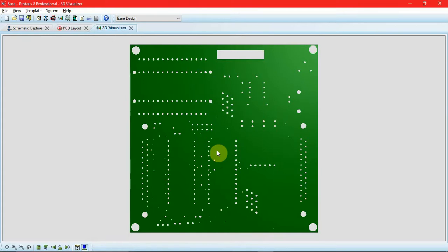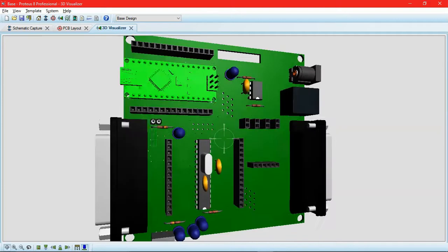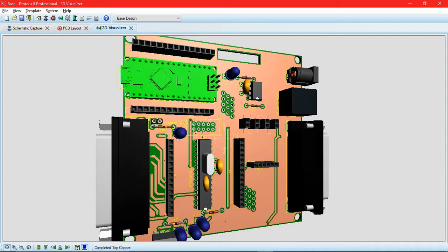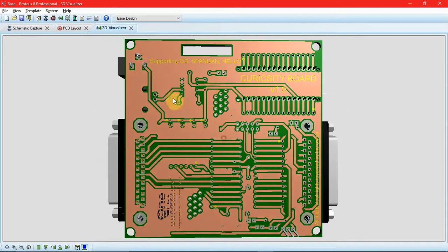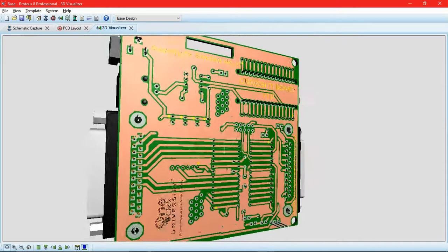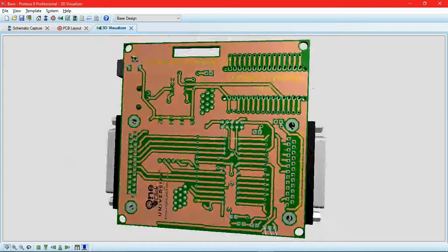So usually, as I said, the solder mask or the resist is of green color. Apart from making the board attractive to impress whoever came to your mind first, the importance of this layer is that it provides isolation to the copper layers from the external environments. It stops any external noise from being included and also prevents short circuiting. So if we remove the solder mask, this is how our copper planes would be vulnerable to the external environment. So to avoid this, the resist layer has to be applied.